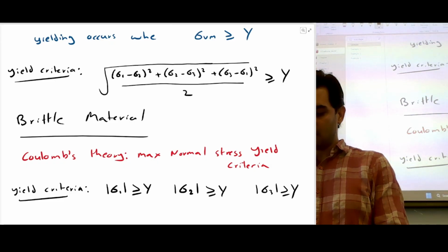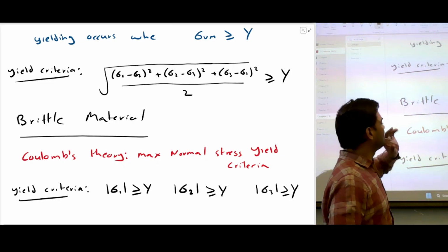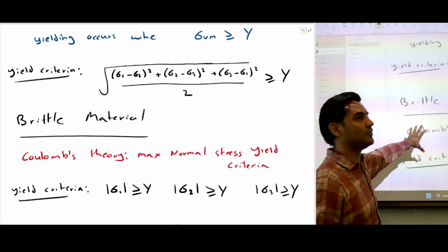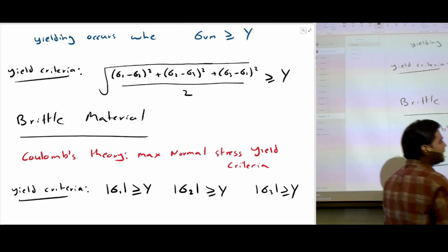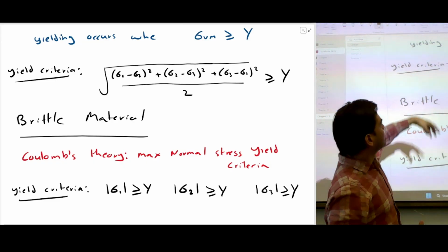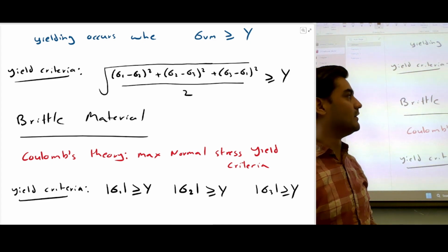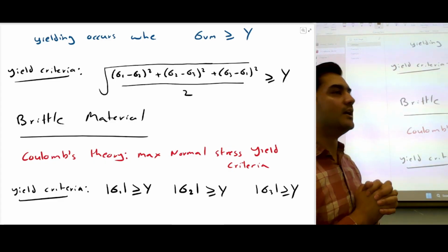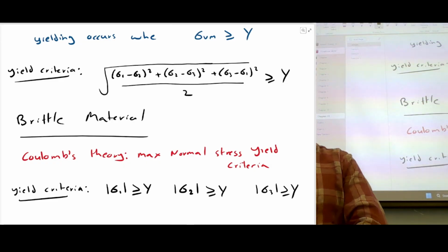And we can just do one example. Once we do it, it's going to get super clear because it's just an extension of Mohr circle and an extension of transformation equations. So the first step is to calculate stress one, stress two, and once we have those, we can just use these yield criteria to figure out if the material under a given loading condition will observe yielding or will fail or not. So we can do example 11.1.